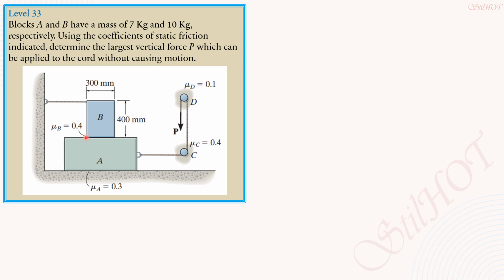The lower value would control, of course, because if you use the higher value, that means the other possibility happens, and that would be in motion already. So for the solution, tension in the tight side equals tension in the slack side e to the mu sub s beta. So let's draw the free body diagram of the upper block B.